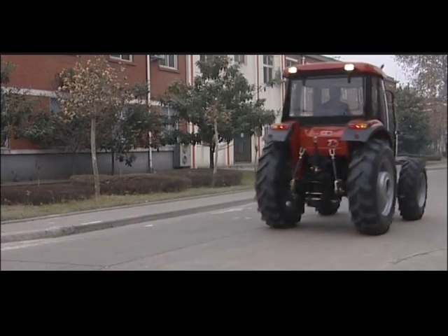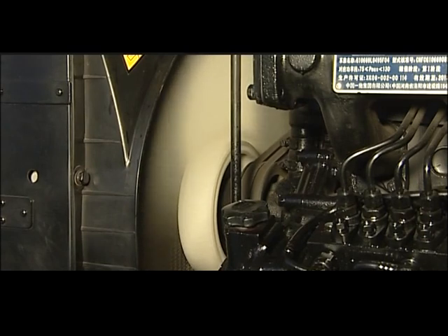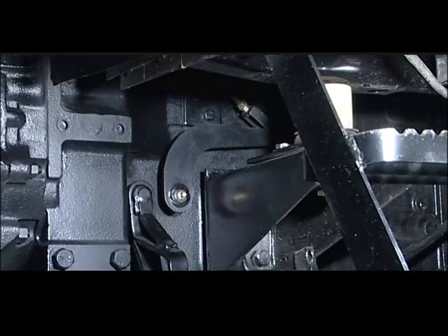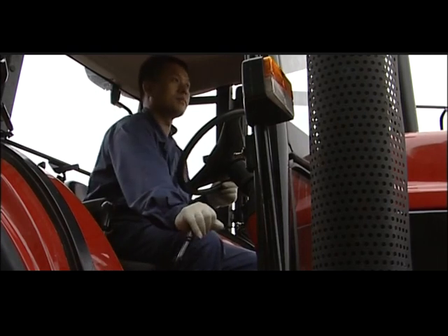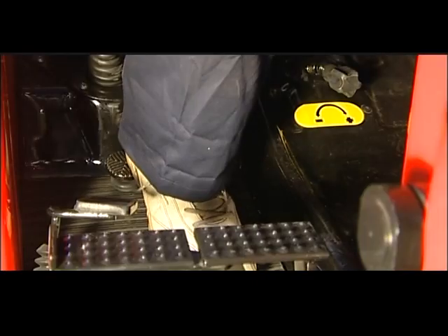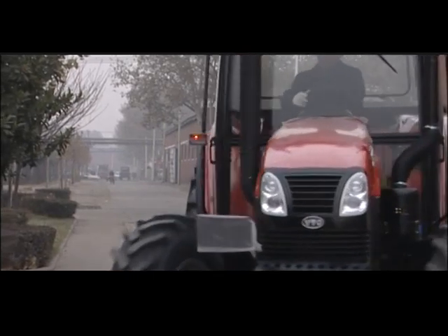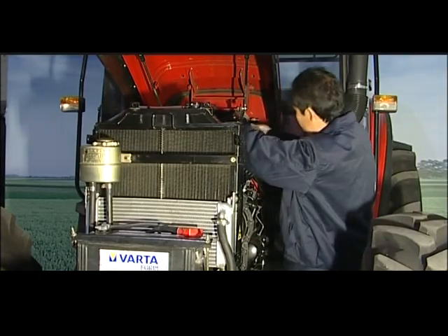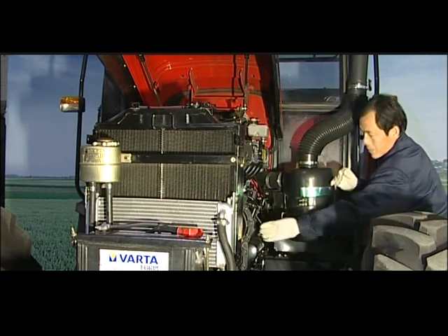Must pay attention during running in whether the readings of all electrical equipments and instruments are normal or not, if the engine is running at normal condition, if the clutch is smoothly engaged and completely disengaged, if the gear change is easy and flexible, if the brake work is reliable, if the engagement and disengagement of differential lock is reliable, if the steering is flexible and reliable, if the front drive axle engagement is smooth. Stop the tractor immediately and remove the trouble when finding any abnormal phenomenon or failure.